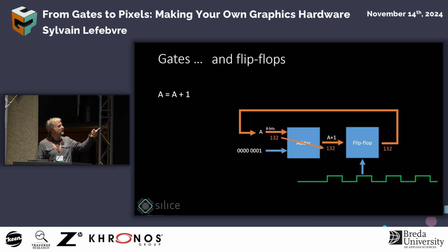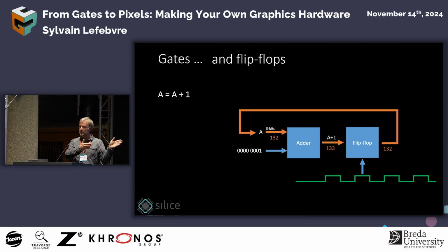And of course, this goes back to the adder, which immediately refreshes the output after a tiny delay that I've shown here by moving the clock a little bit. But this delay is much shorter than the clock period, hopefully. The flip-flop keeps this value until the next tick. And as it does this, the circuit is now stable.